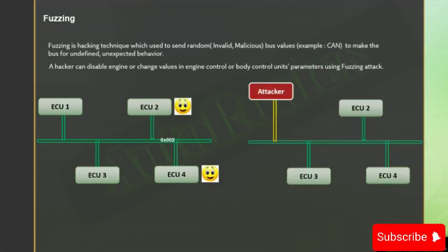Let's look at an attacking scenario here. Let's say the same architecture is present, but an attacker has injected his mechanism to send some messages in the bus. It is really possible. If he is able to attack the bus systems via any channel, let's say from infotainment, he can inject some CAN messages, based on what he understood from sniffing about the values to be sent. The 002 arbitration message will also be flowing in the vehicle, and the attacker also sends the same message at different intervals.